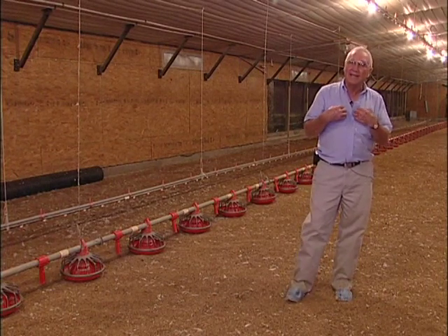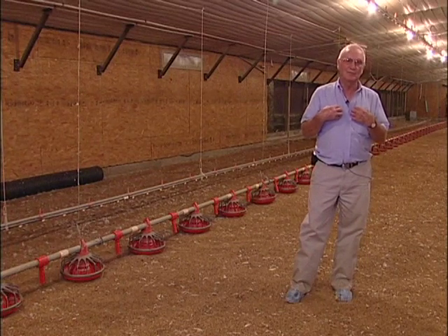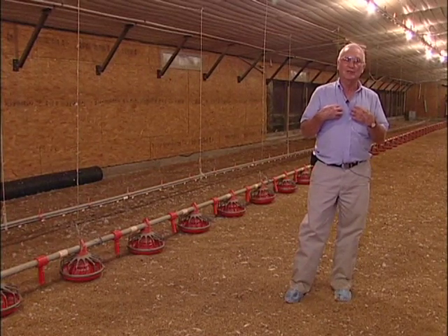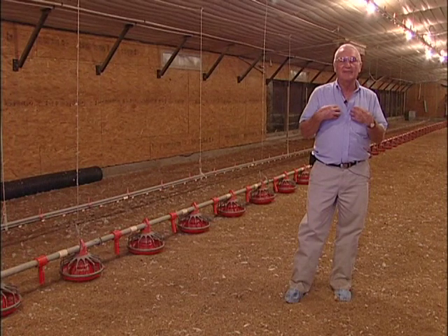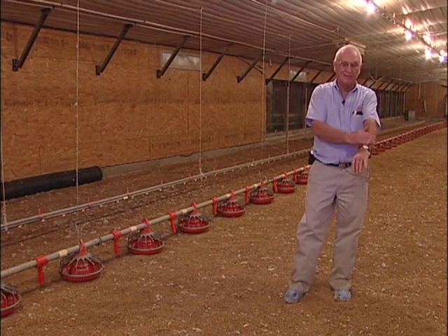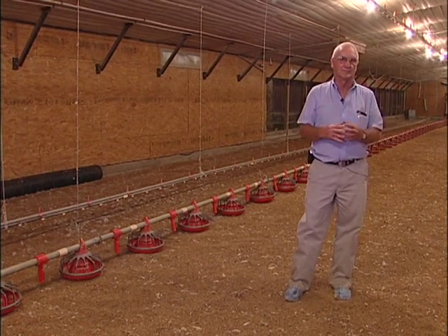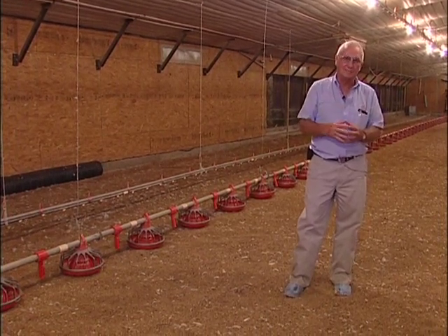Now, if we stand in front of the pads, we would feel like we were getting a tremendous temperature drop because we have the ability to sweat. So we feel the airspeed, and we feel the evaporation of the moisture off the surface of our skin. Chickens can't do that.